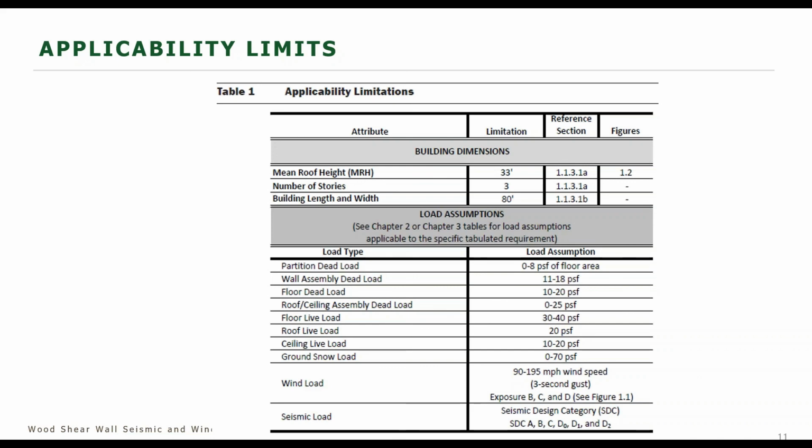There was a question about blocking orientation. If you have a blocked shear wall, what is the orientation of the blocking? It is not important. There's not a specific requirement on which way the blocking has to be oriented. You do, however, need to make sure that you meet the minimum penetration requirements on the blocking, so that is something you may need to take into account. But it does not matter which way the blocking is oriented in your wall.